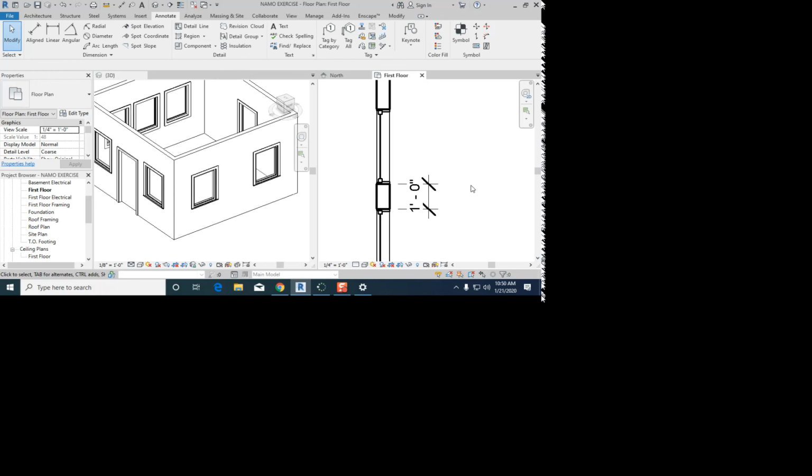Okay, I think what happened, when you moved your windows, you kept the constraints. So now it's basically saying you wanted to keep your windows here, I'm not gonna move them. See how it's mad? Constraints are not satisfied. I'm gonna put remove constraints. Okay, and then down here I'm gonna do the same thing. I'm just gonna move it. Since we already removed it, it's not mad at us. But now I guarantee you that it will work.